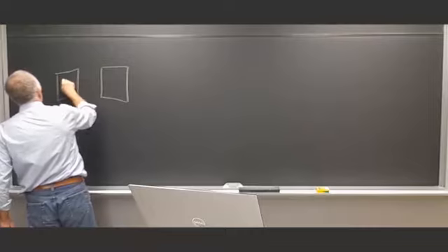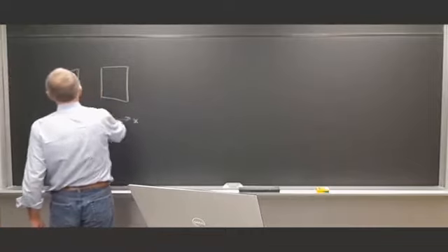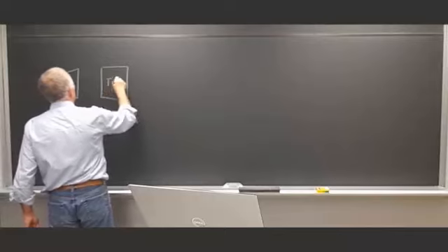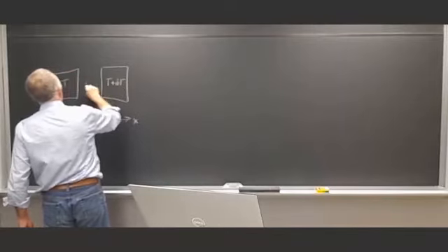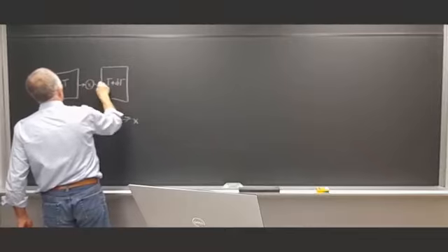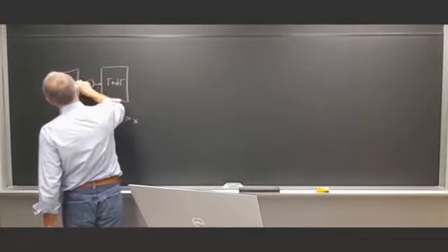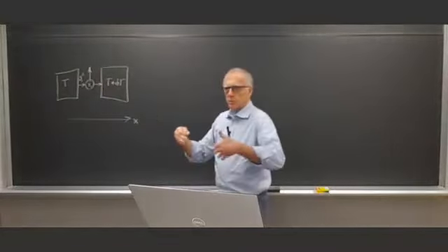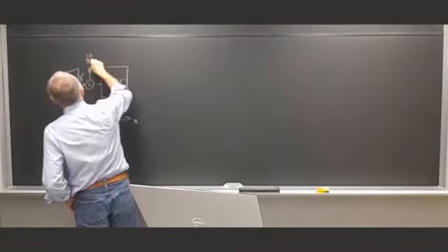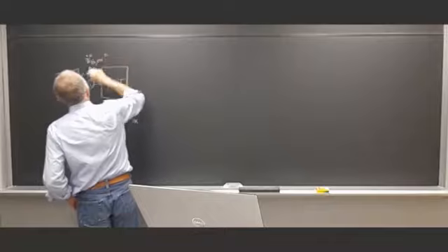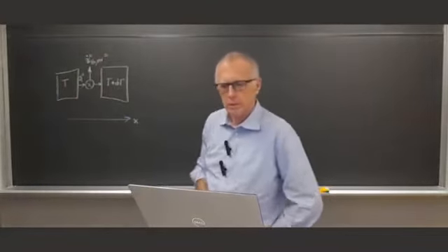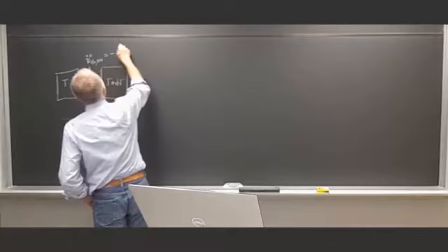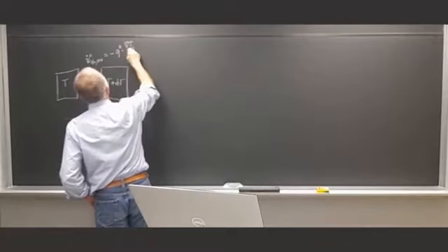So we had here this is x, here is T, and here is T plus dT, and then we put in an engine that receives a heat flux, like a Carnot engine with the Carnot efficiency, because it's a reversible engine, produces a W, let's call it W thermal reversible, which is given by minus Q gradient in T over T.